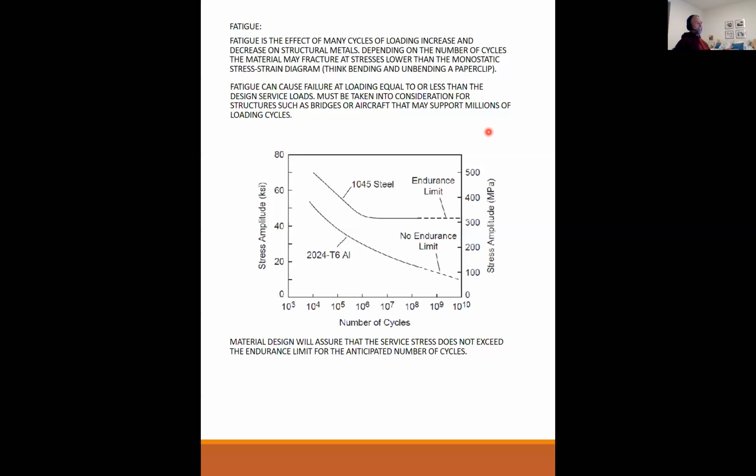For creep in concrete, why is that? Why do they always cure it first? Yes, one of the reasons, yes. But the point of the concrete example is the longer you can let it cure in days before you put load on it, the less problem you'll have with creep. So if they want to build a building really fast and pour a new floor every week, you've got to be careful about the creep problem. If they slow it down a little bit and only start pulling the formworks out and loading it after really letting it cure for a month or so, it'll really cut down on that problem.